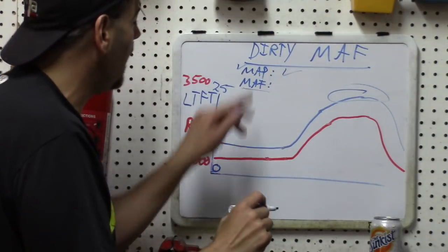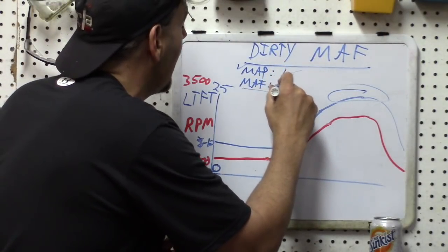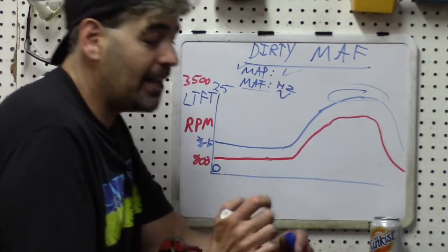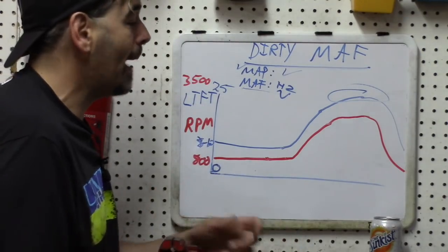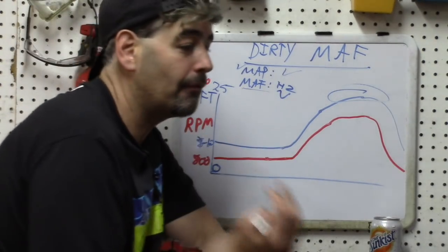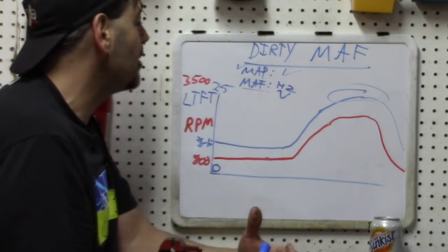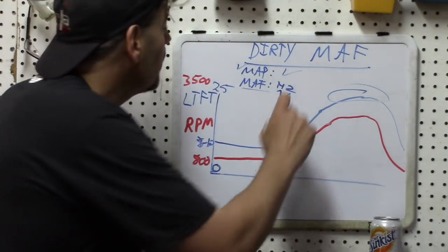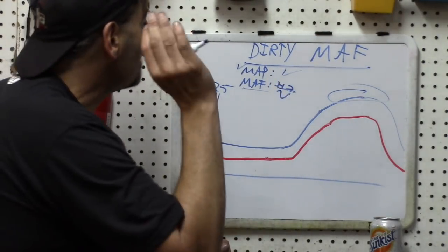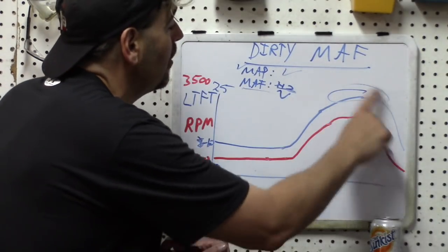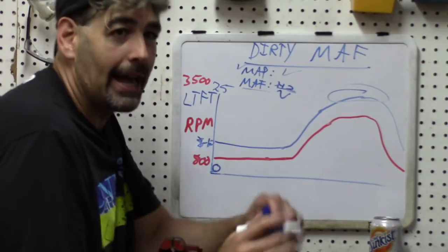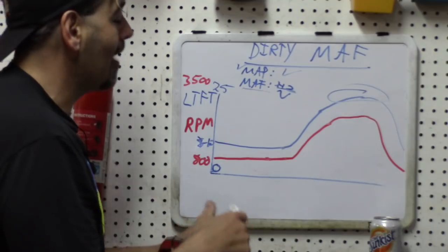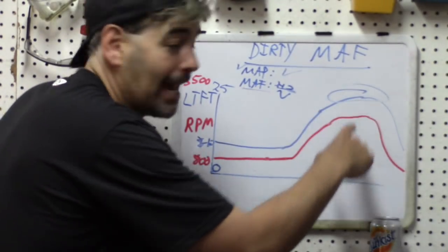But if this checks out okay, then what I'll start looking for is my frequency or voltage using the scan tool on the MAF sensor and seeing if those look a little bit low or out of spec. Now, of course, this requires you to have some baseline information, but on most GM models, if I see anything under 1800 hertz on my scan tool, I'm very strongly going to suspect that this is caused by a dirty mass airflow sensor, and I'll clean the MAF sensor, recheck my data after that, and verify that my short-term fuel trims then start negating my long-terms.